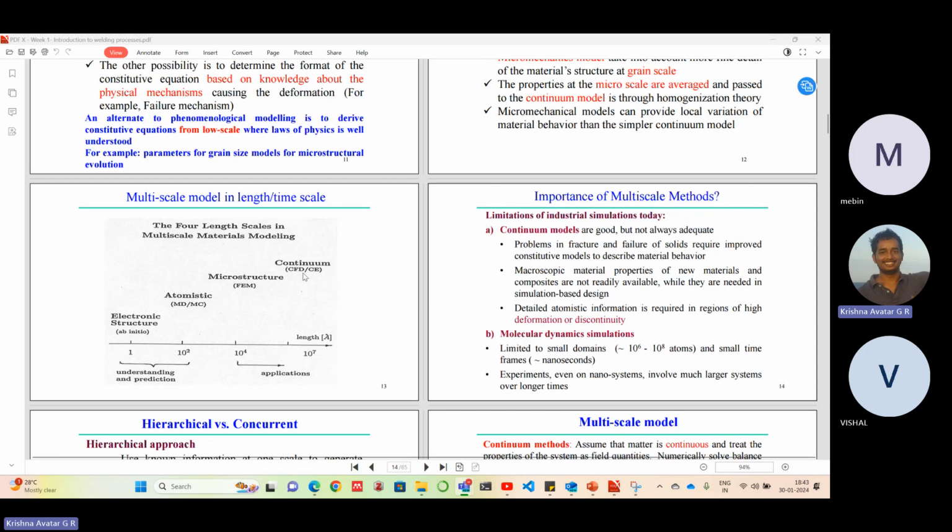There are various techniques here as well. If the system happens to be very simple, say 1D, then we could use finite difference for a simple setting. And if the geometry happens to be complex, then we will have to use the finite volume approach or even finite element approaches to solve fluid mechanics problems.